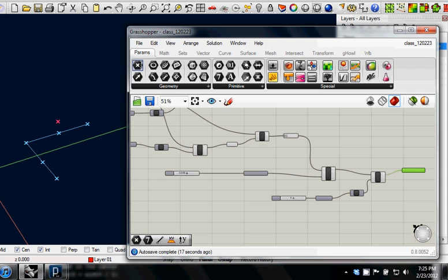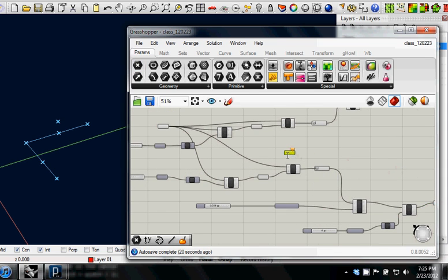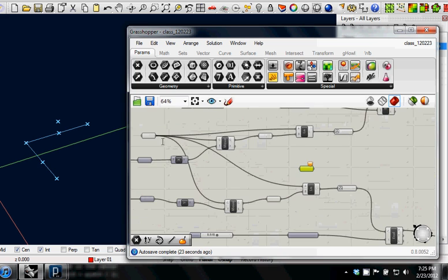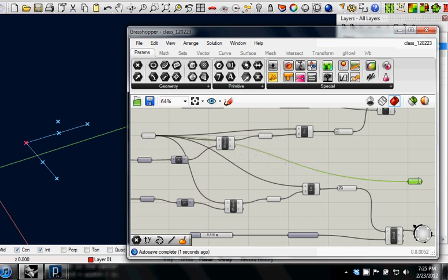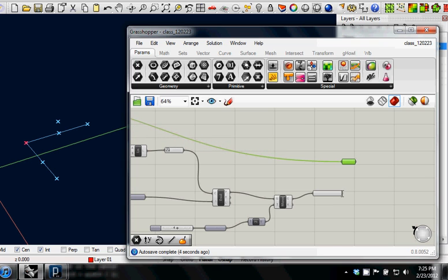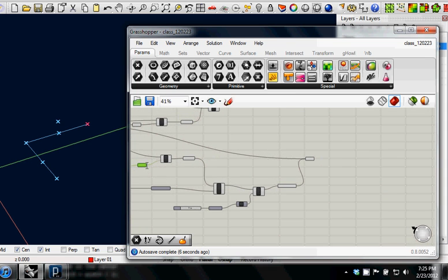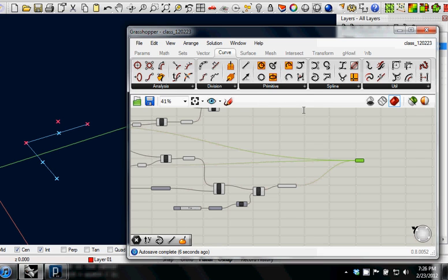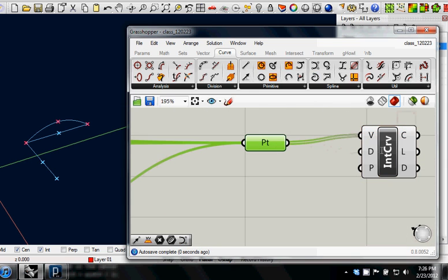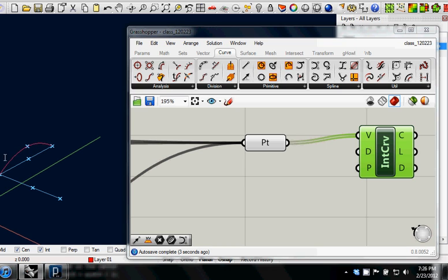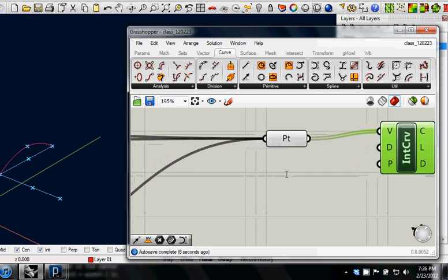And then if I wanted to, what I could do is I could make a point parameter, and I could dump in my origin in this order, the origin, right? Then hold down Shift, the intermediate point, and then hold down Shift and the Y end, right? So now I have a list of 3 points. And I could use that list of 3 points and interpolate it to make a new curve. All right, so I now have a parametrically controlled curve on the y-axis.